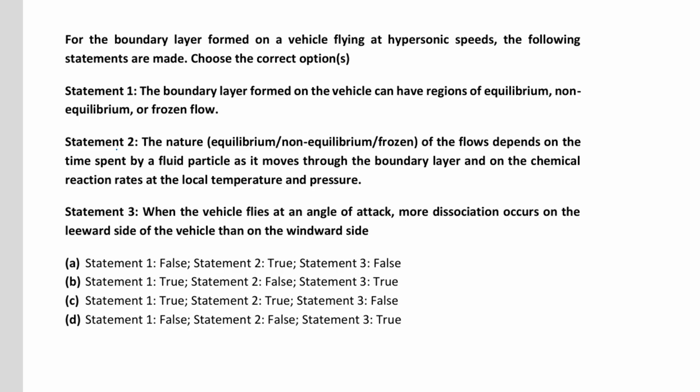Statement 1: The boundary layer formed on the vehicle can have regions of equilibrium, non-equilibrium, and frozen flow. Statement 2: The nature of the flow, equilibrium, non-equilibrium, or frozen, depends on the time spent by the fluid particle as it moves through the boundary layer, and on the chemical reaction rates at a local temperature and pressure. Statement 3: When the vehicle flies at an angle of attack, more dissociation occurs on the leeward side of the vehicle than on the windward side.